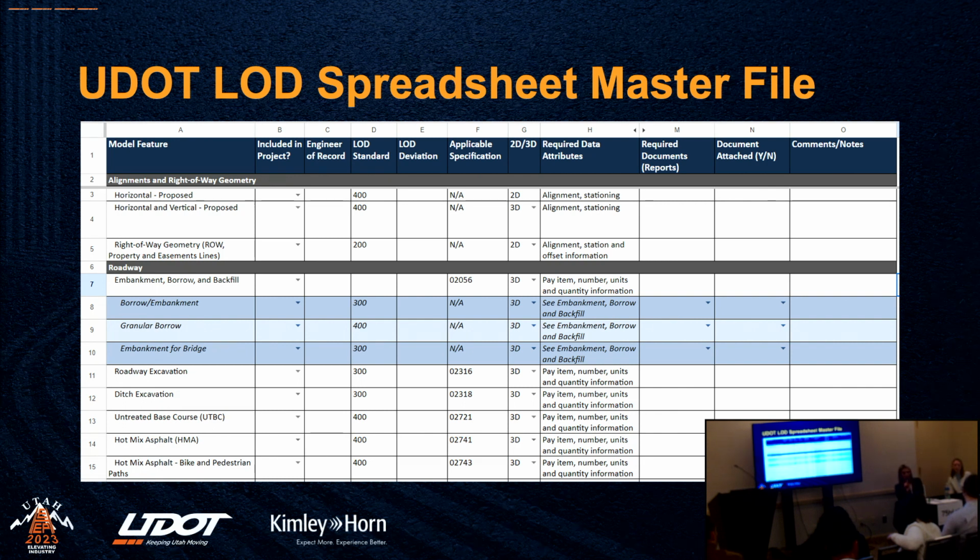I would say quite the opposite. Contractors have been putting ped ramps in for years and years, and they don't want us to dictate how, because they want the flexibility of meeting the standard. At UDOT, they have very well-defined ped ramp standards, so as a designer, it's a little easier to point them back to those. I don't know if that's something we would consider in the future if the tools got a little better. The hard part with ped ramps is you have such small tolerances, and if your survey is off by just a little bit, those tolerances are incorrect. So there needs to be a little flexibility because of those tolerances in the field.